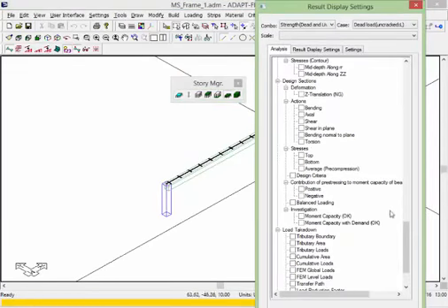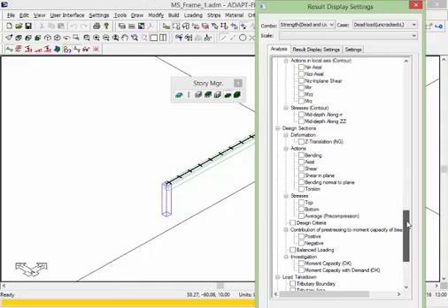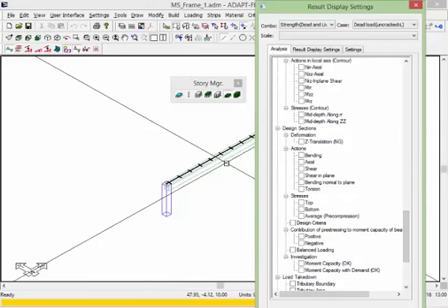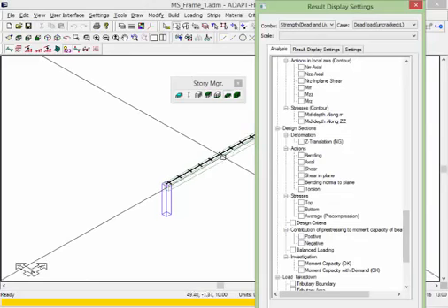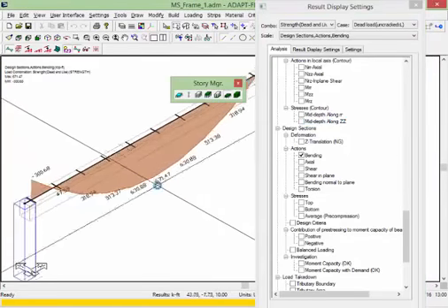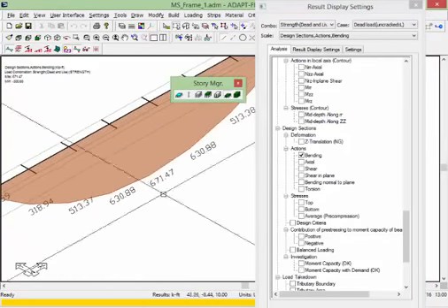If you recall, the beam element moment was 672 kip feet. Now I'm using design sections, which utilizes integration of nodes, either frame or shell nodes. And for this case, we have a moment along this strip of 672. So this should be identical to the beam moment.